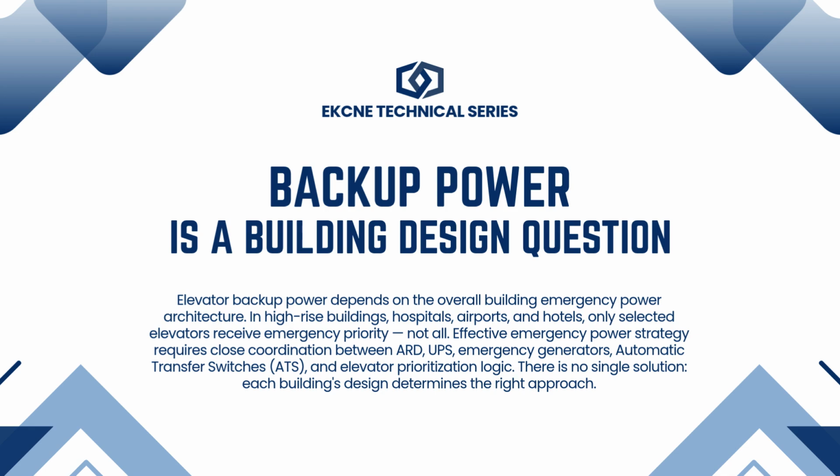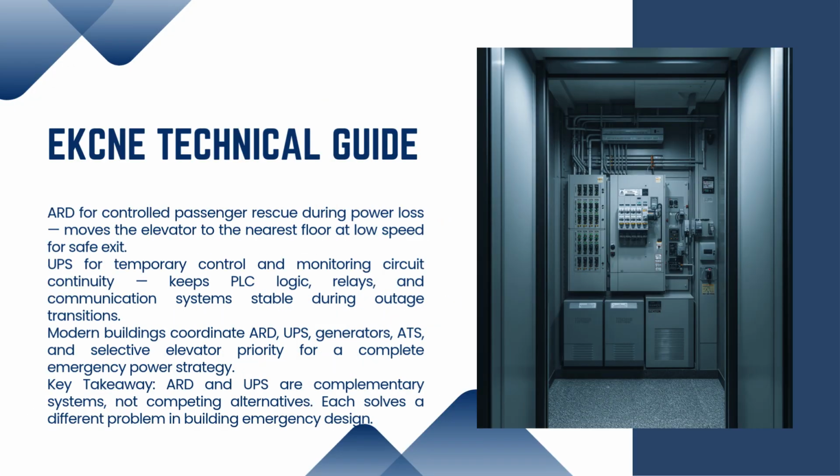In some high-rise buildings, hospitals, airports, hotels, and transportation hubs, only selected elevators may receive emergency priority, while others remain unavailable until generator power becomes stable. This is why elevator backup power is not just an elevator equipment question. It is a building emergency power architecture question.